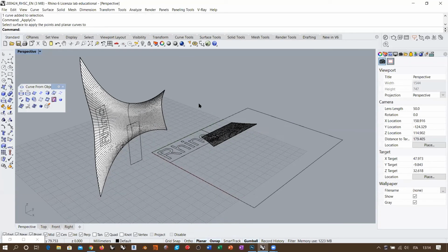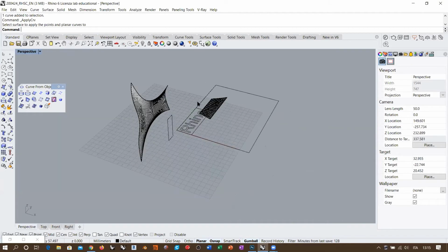If I understand well, when we speak about topological deformation, it's a parametrical consideration. Yeah. Actually, this is a different meaning of parametric. In Grasshopper, parametric means that you work with parameters that affect the final result. But in this case, we are referring to the parametric representation of the surface, which for the curves is the famous T parameter, which represents time. But as a surface is a two-dimensional domain, you have U and V, and eventually W that determines the direction of the positive normal.